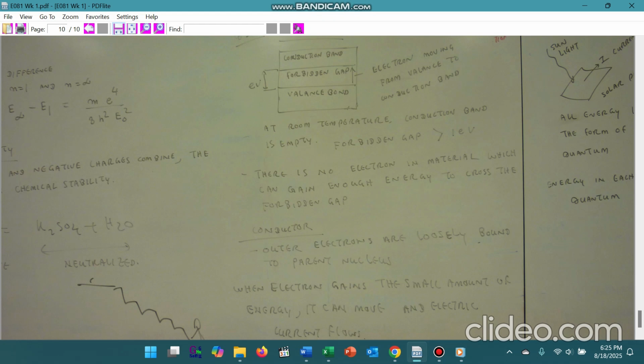Normally glass is a very good insulator. When the electric energy is too big, about 30 kilovolts, 40 kilovolts, then electrical current can pass through the glass. Similarly, paper is normally an insulator. But if you touch this paper to 1 kilovolt electricity, the paper can be burned out because of too much electrical current, so the forbidden band is totally destroyed. This is the kind of insulation breakdown.